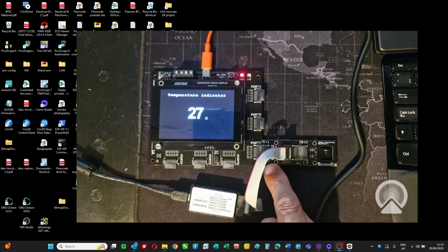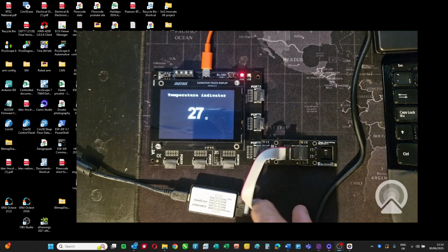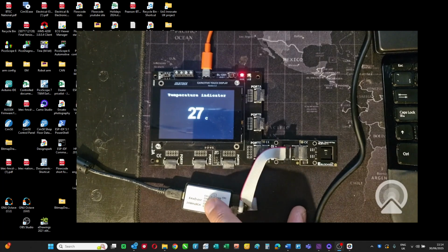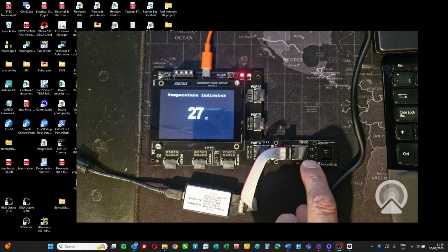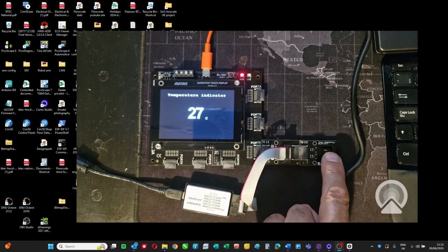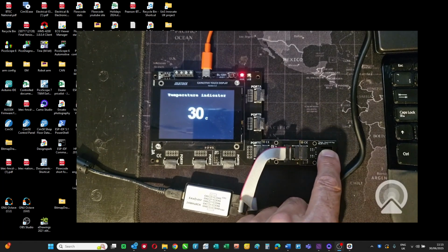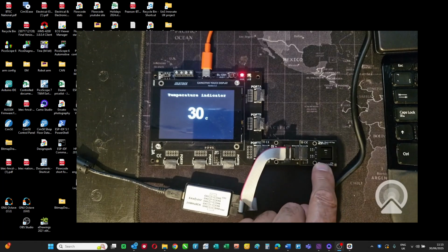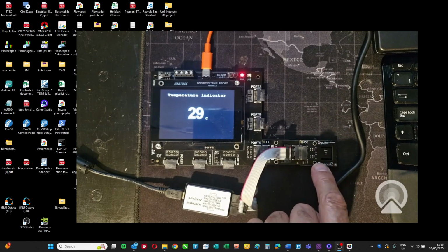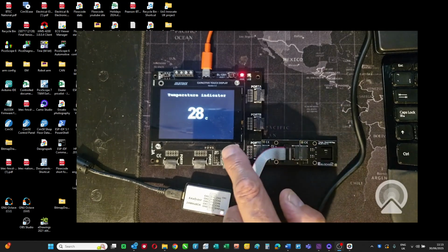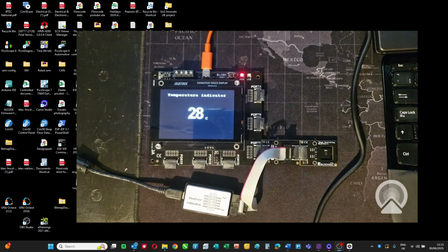And in series with it on port C, we've got a little interface board and a logic analyzer, an 8-channel logic analyzer, and we'll look at that in a moment. The program takes in the temperature digitally and displays it on the circuit board. It's a very warm day here today, about 27 degrees in my office. So when I put my finger on it, it's not moving a great deal, but you can see that it is working, and the program shows the temperature on the display.